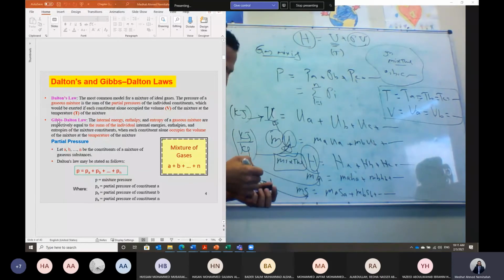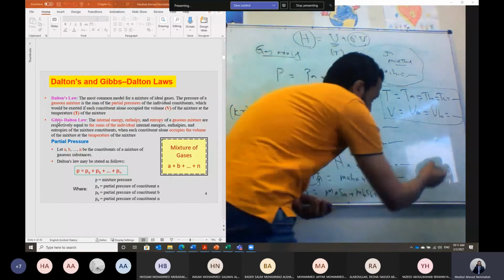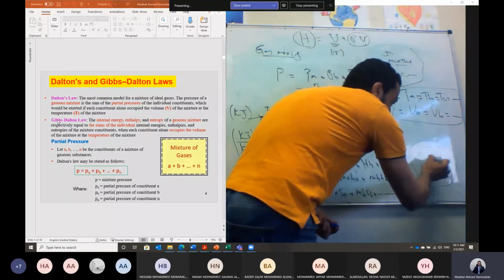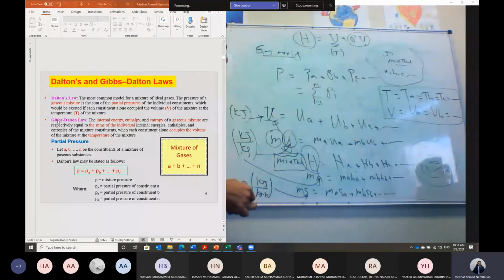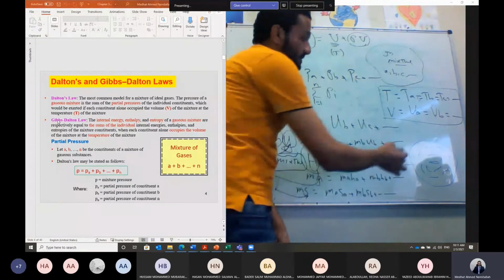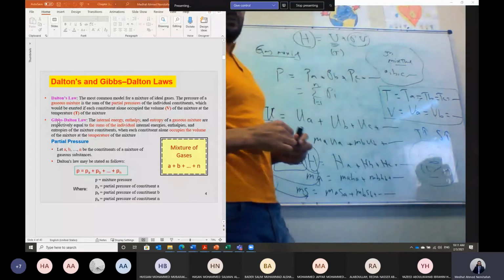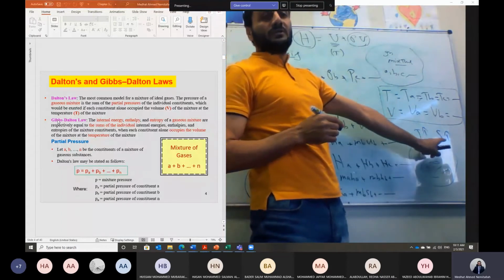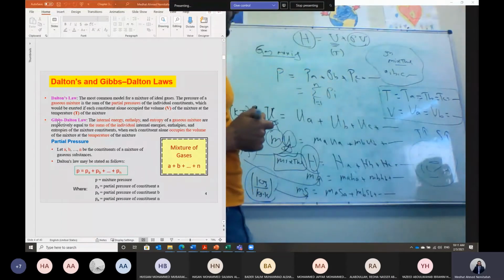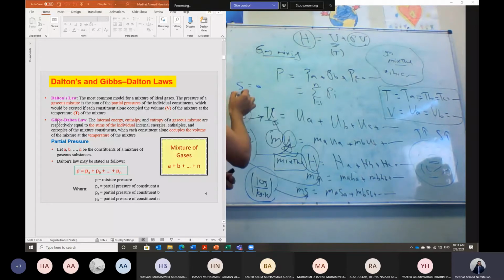If you ask anybody what entropy is, he will just tell you the entropy is a measure of randomness. If we have a gas inside a container, it will give us an indication about the random motion of the molecules. And if the temperature of the gas is high, that means it should have higher activity of the molecules, and in this case the entropy should be higher. Based on the third law of thermodynamics, the entropy is assigned the value of 0 when the absolute temperature is equal to 0 Kelvin. This is the third law of thermodynamics.